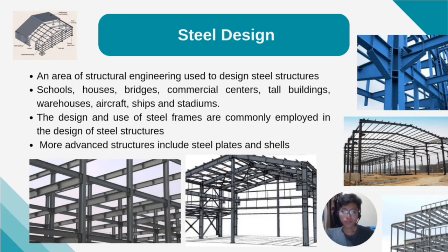The depth of steel beams used in the construction of bridges is usually governed by the maximum moment, and the cross-section is then verified for shear strength, near supports, and lateral torsional buckling. This is done by determining the distance between transverse members connecting adjacent beams. Steel column members must be verified as adequate to prevent buckling after axial and moment requirements are met.